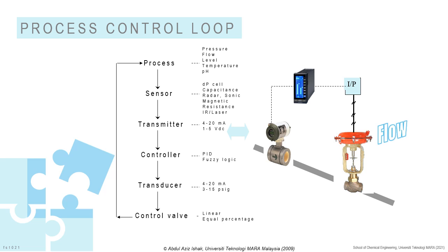Finally, the final control element, that is a control valve, implements the real-life solution decided by the controller by taking in the input signal and transforming it into the equivalent operation performed in the process. It performs the required changes in the control variable to make it equal to the set point. If any changes ever occur again, then the loop starts again.